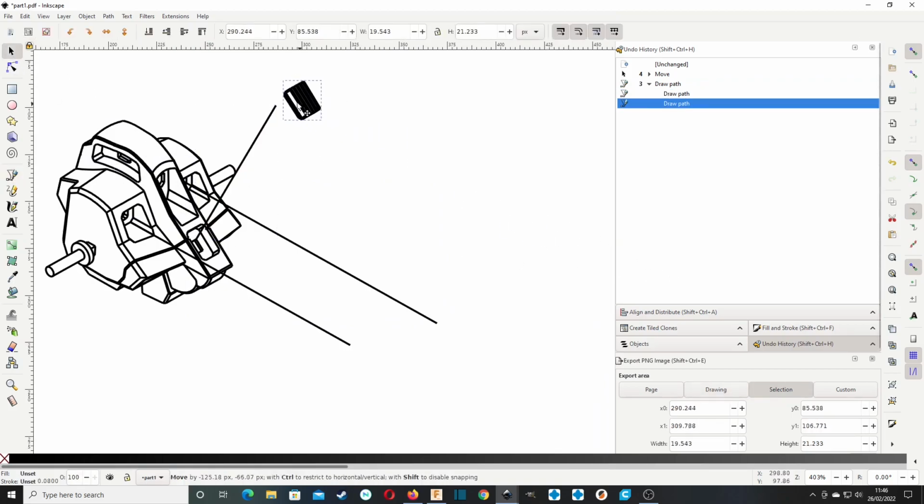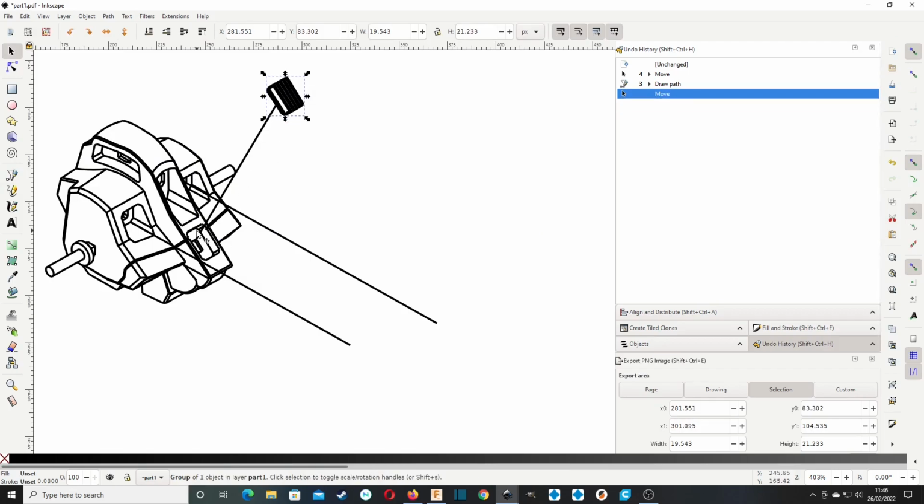This part has to go in this way. It goes in from the top, so you would show the line coming from the top down, and you've got this part coming in from the side. These lines cross over. That creates problems. It might be a case that people go, oh, it goes in like that and that. Now, you and I might go, oh, no one would actually think that. But if there's any possibility of someone doing something wrong because of your instructions, redo the instructions. Take an extra page, do whatever you have to, but do not cross the lines where you can.